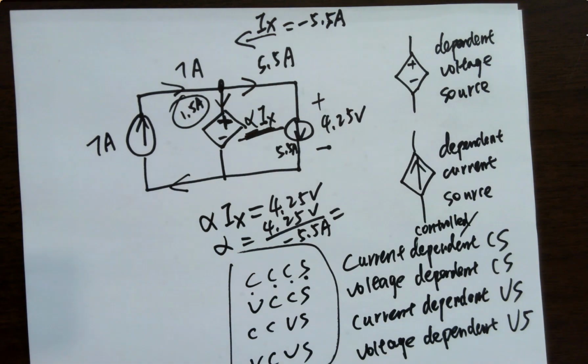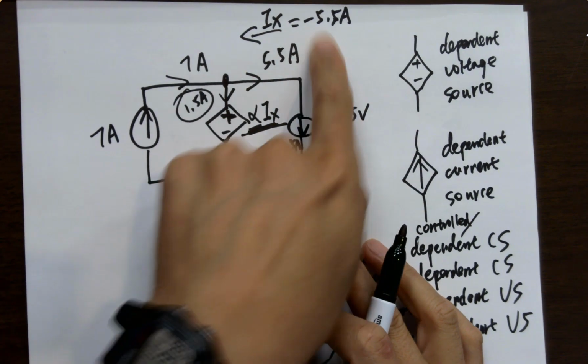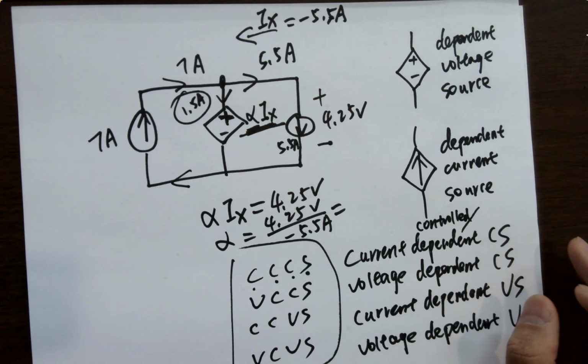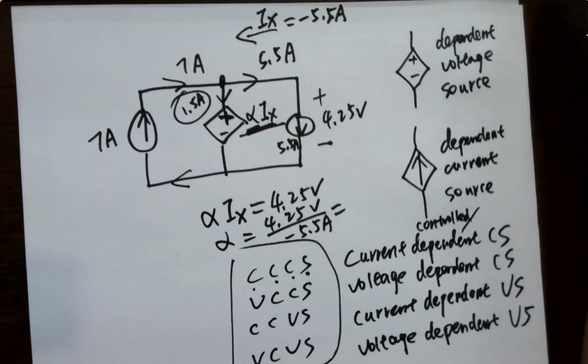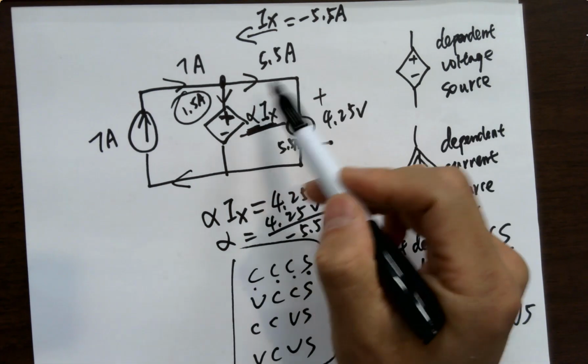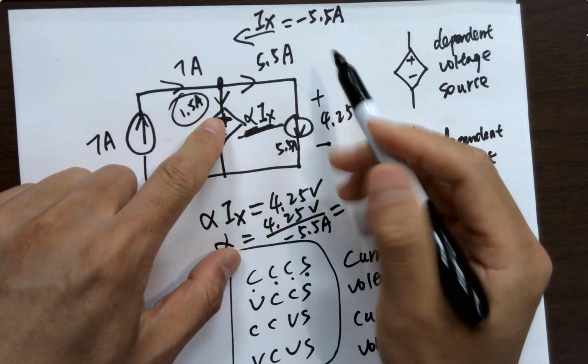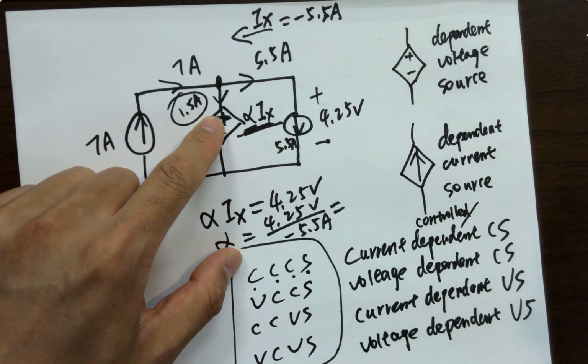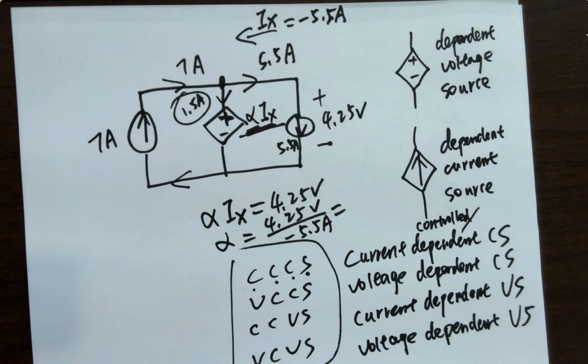Just want to let you know it depends on something. And practice your Ohm's law, KCL, KVL skills. There won't be anything like a voltage source depending on current flowing that way most of the time. But you do have dependent sources in the future. If you take advanced circuits, there will be transistors, where the voltage or the current across it depends on the voltage somewhere else. It happens. But not these specific cases. Sometimes they have a current here but a voltage super far away from it, and it depends on that little resistor's voltage drop. It doesn't make sense. It's just a model. It just tells you how to deal with it.